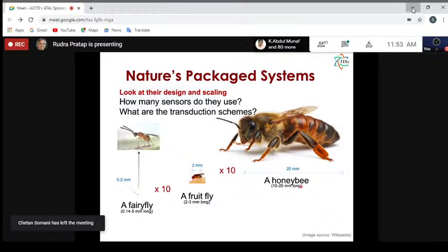Touch screen sensors are precisely that. You have a screen which, if you touch, it has a flexible membrane on top, and when you touch, it flexes, and behind that there are electrodes, arrays of electrodes, and at the point you have touched, the capacitance has changed, and that's what you get into your system as a signal, from which you figure out at which coordinate somebody has touched, and that corresponds to what key or command or whatever.